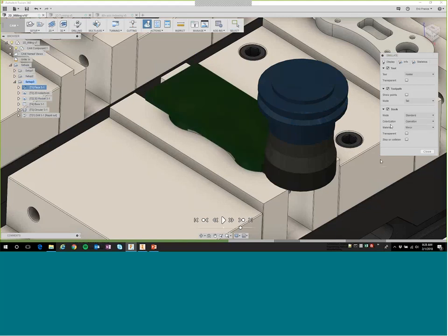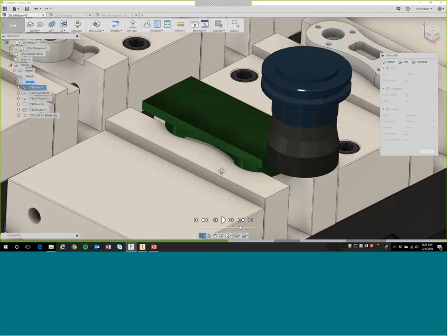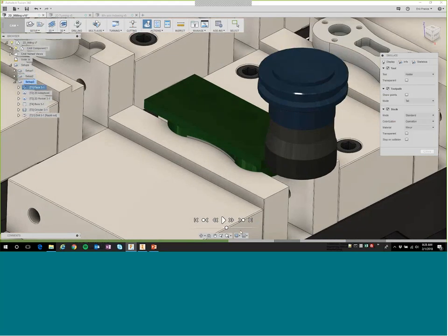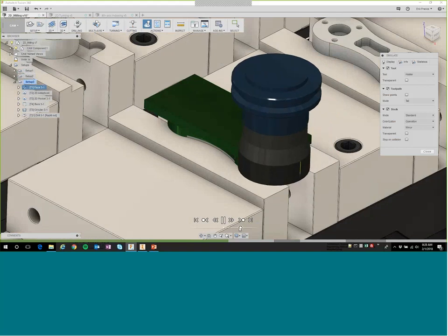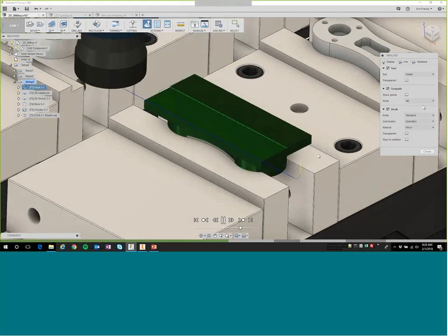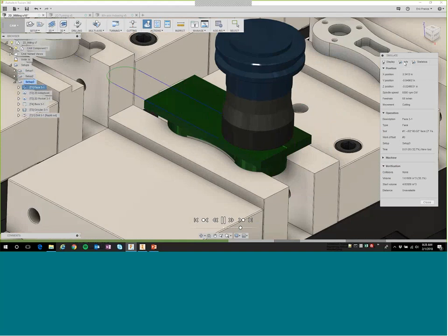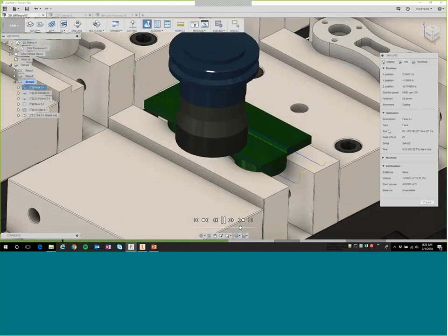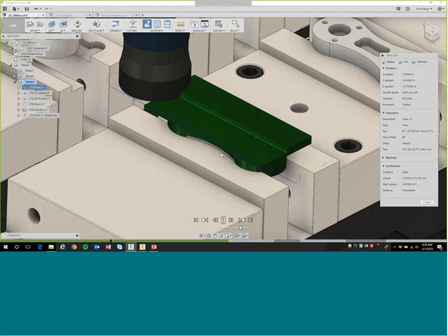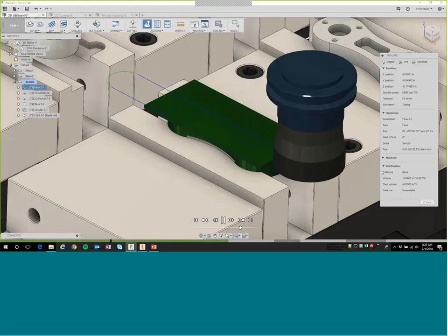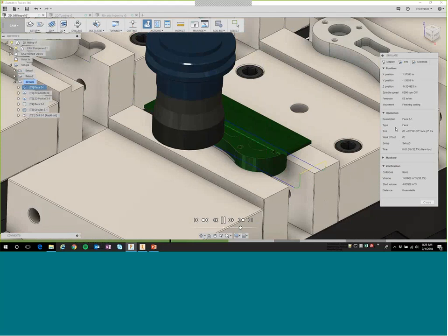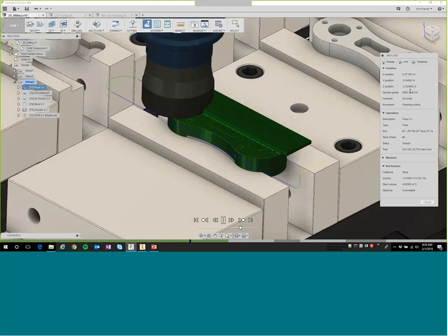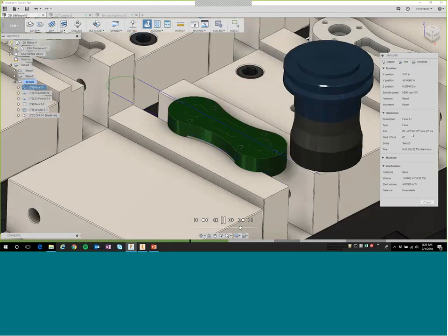So in this case, right, you can see the stock that's in there, but we're going to start out with a milling operation again to go through and remove that material. Right, and we'll kind of speed this up, but we're going through and making a couple passes. A couple other things to look at, right? So we've got the info tab where we can see which operation we're in and get the data as we're moving through: the position, spindle speed, feed rate.